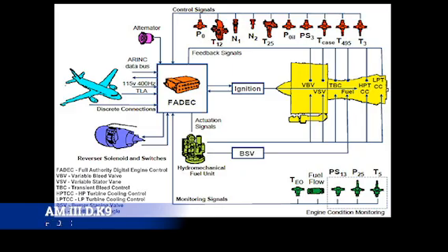Now it does have its limitations. It's relying on electrical power primarily. That's one of the big kind of scary bits, and that's why there's like the RAT, there's TRUs, there's all these different ways to maintain electrical power to the engine. Because if you lose the engine, you start losing like all systems. That becomes like kind of like the center of gravity that just falls apart. If we lose both engines and the APU, then you're on battery power or the RAT's power alone.